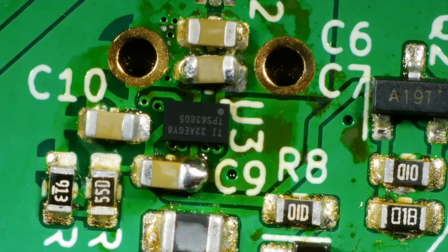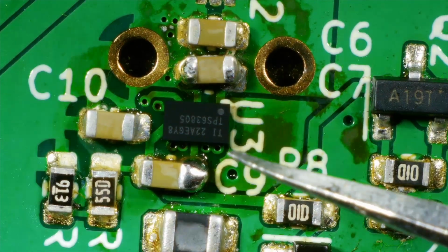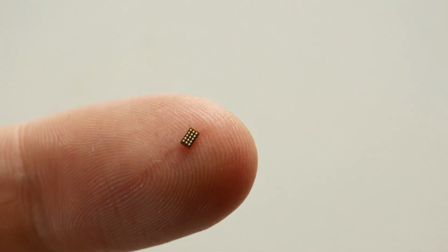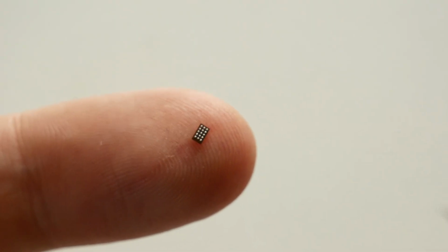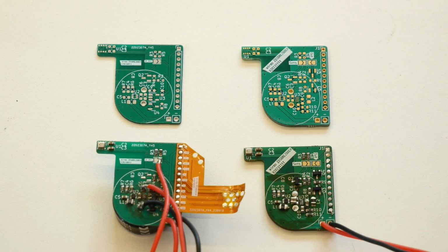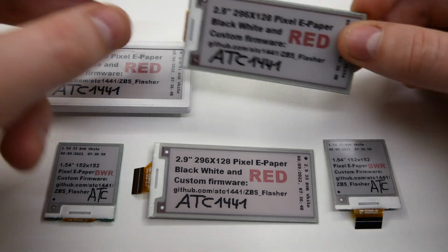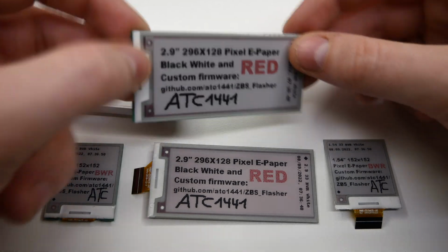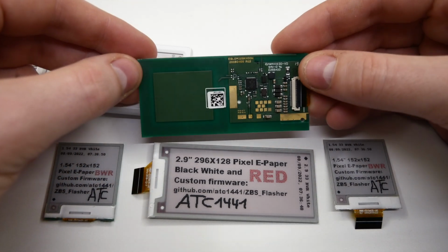First of all, energy harvesting is really hard as every microampere of current counts. Secondly, those small BGA parts suck. And finally, take more time thinking about the circuit and elaborate on it before ordering a PCB. This leaves me off basically where I started, but I already have some more ideas for a new circuit.